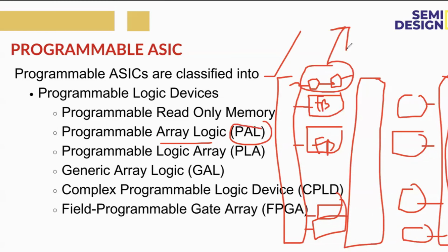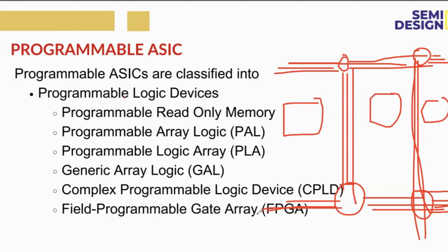So here some of the switches will be there. Through the switches we will connect everything, or we can also call them interconnect blocks. These switches we can call interconnections. Now, how are we using interconnections at the SoC level? AXI interconnects, AHB interconnects, like that we are using. But in FPGAs, we use the switches as the interconnects.